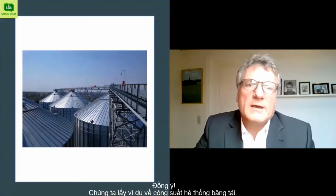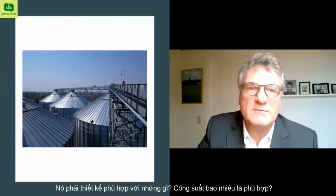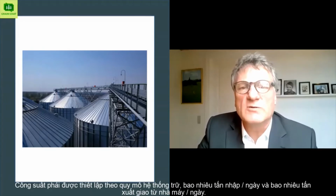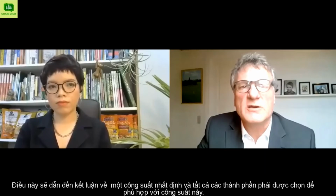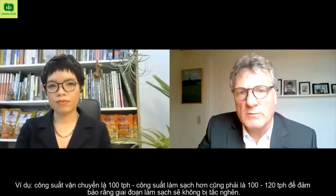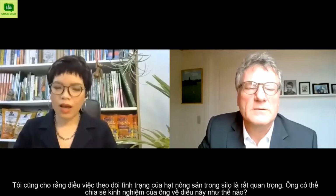Right. Take conveying capacity. What should it match? What should be the capacity? If it is a very big plant, the conveying capacity should be big too. The capacity must be set according to the storage size: how many tons are received every day, and how many tons are delivered from the plant every day. This will end up in a certain capacity, and all components must be chosen to fit this capacity. For example, if conveying capacity is 100 tons per hour, the cleaner capacity should also be 100 or a bit more, to be sure that the cleaner will not be a bottleneck. Yeah, I agree with you.